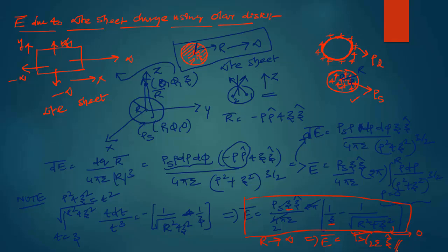In this particular way we can derive the electric field intensity in 3 ways. So the summary I will give here. The overall concept is about getting the electric field due to an infinite sheet charge. So what did we get? E bar is equal to rho s by 2 epsilon a n cap.